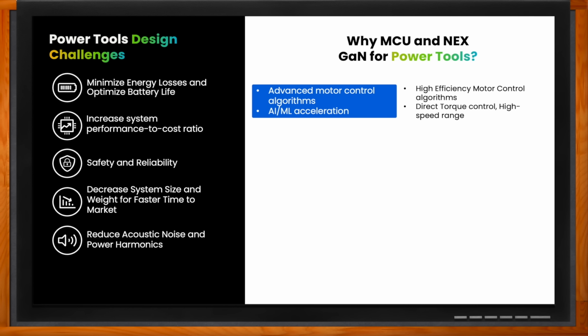So it's a real-time adjustment for what that motor has to perform depending on the application. Direct torque control is much easier to use than field-oriented control, which is FOC, and it's gaining popularity even though direct torque control is older than FOC, but that gives you an idea of the high-speed range and the high-torque range capabilities.